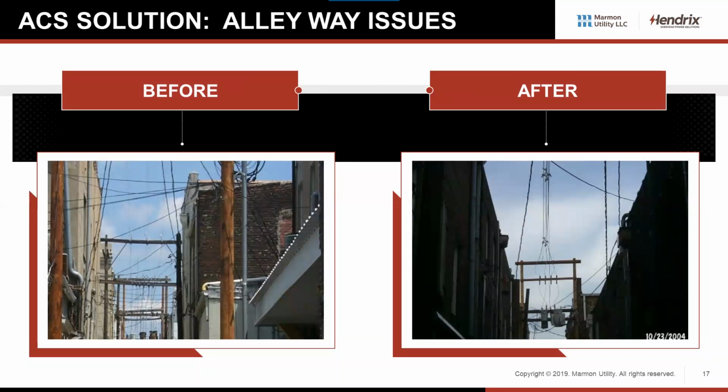Like I said, alleyway construction is where utilities are starting to take a look at how to upgrade their system. How do we improve the reliability in the most cost-effective way possible? Now, we understand that, ideally, you would bury all the conductor, but that's just not practical in a lot of applications. So converting it to spacer cable or covered conductor is always a good place to actually save you money.